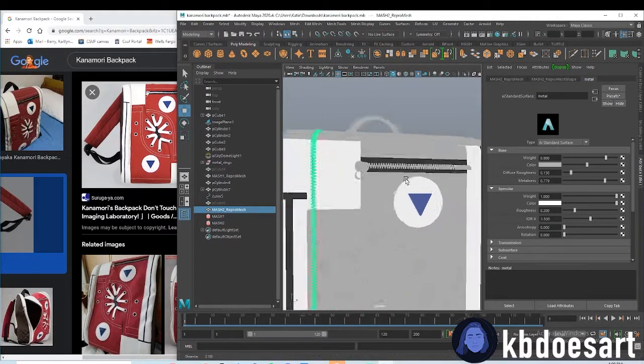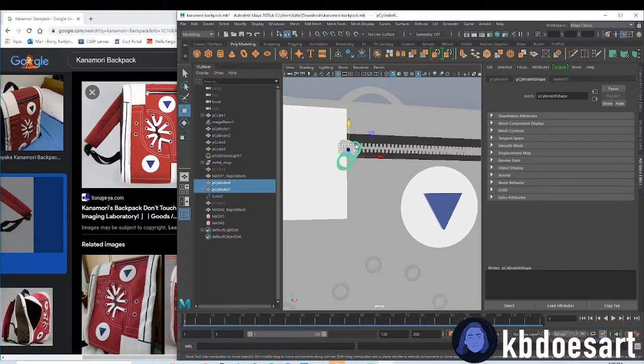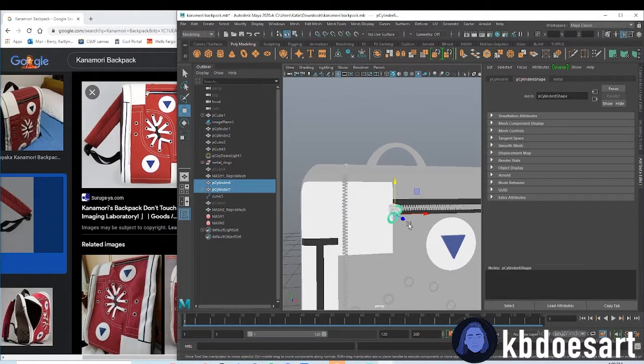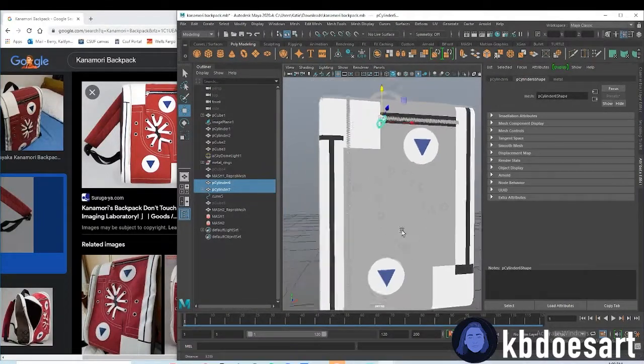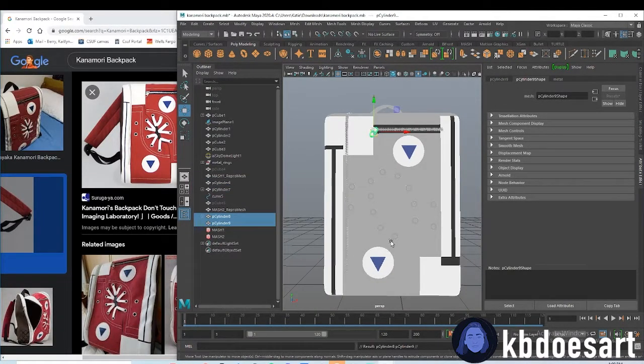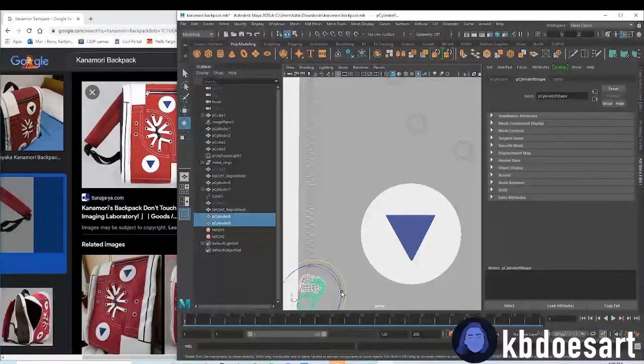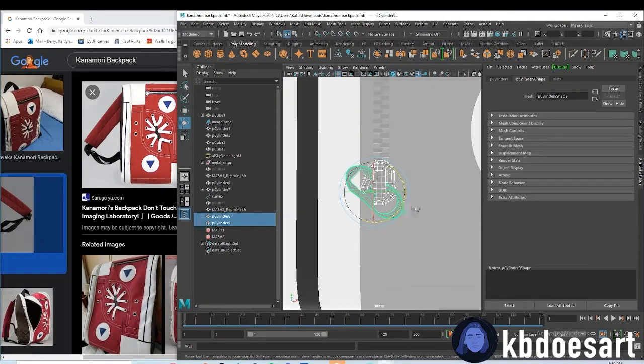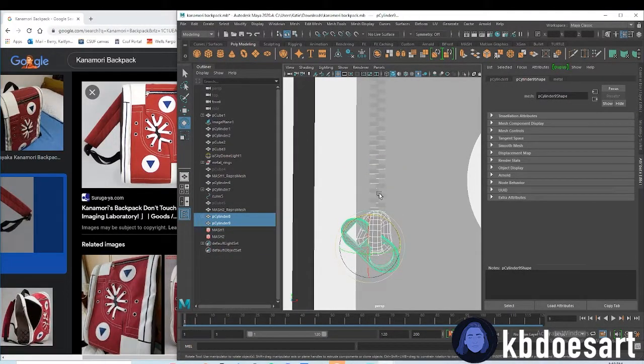You can also apply the metal texture to our other piece of our zipper. And then I'm going to just duplicate that, and we're going to use it down here. So press E, rotate that, let's move it on up, and then you can just move this piece to clip on the bottom.